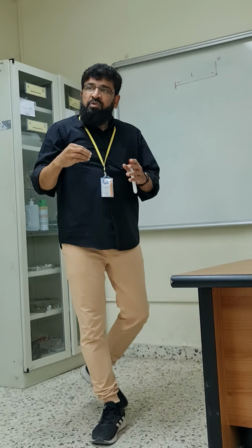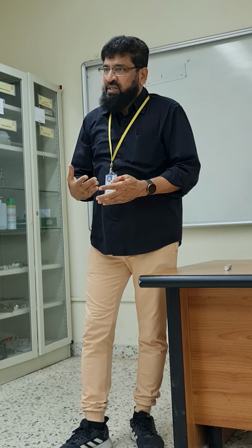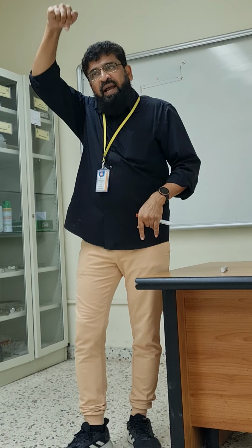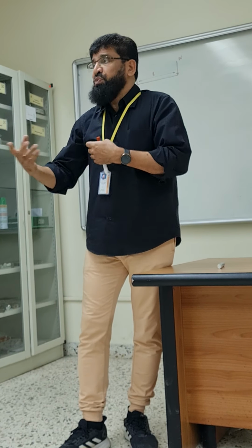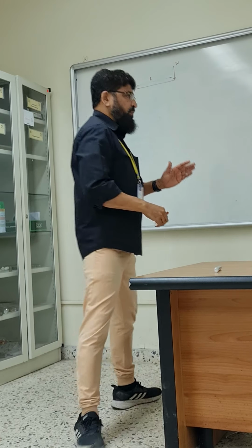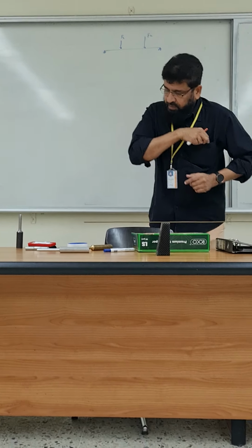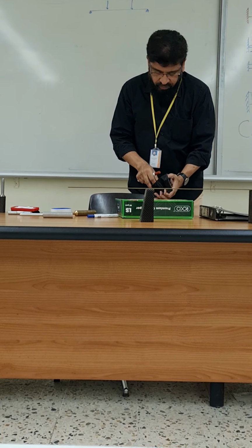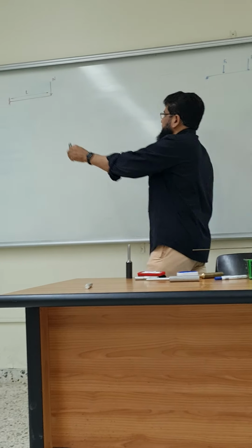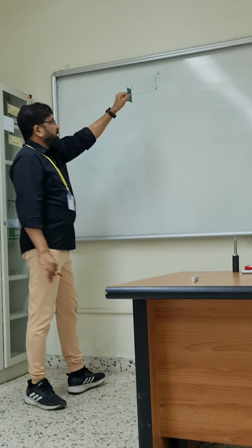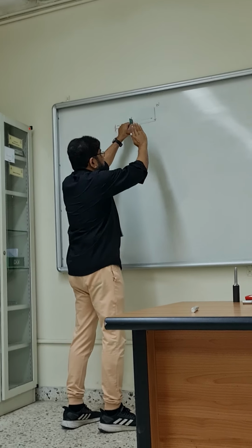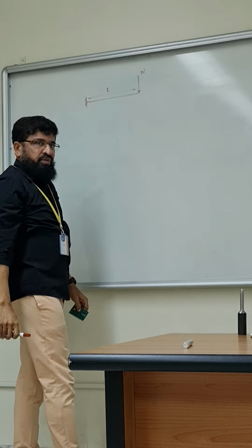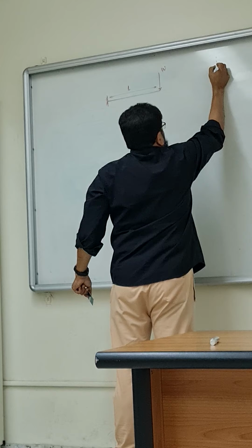Now the question. We have to now come to sign conventions. Now I will tell you what are the sign conventions, which is positive, which is negative. Because forces can act from up to down and from down to up, isn't it? We need to make sure. Is this clear? Which one we take positive, which one we take negative. If I take any point, any center point like this, this is my reference line, I will keep here. This is my plane, okay? On the right side, if I am calculating and doing the analysis on the right side, anything acting downward I will take as positive. Okay, Shubham? This is my reference plane.